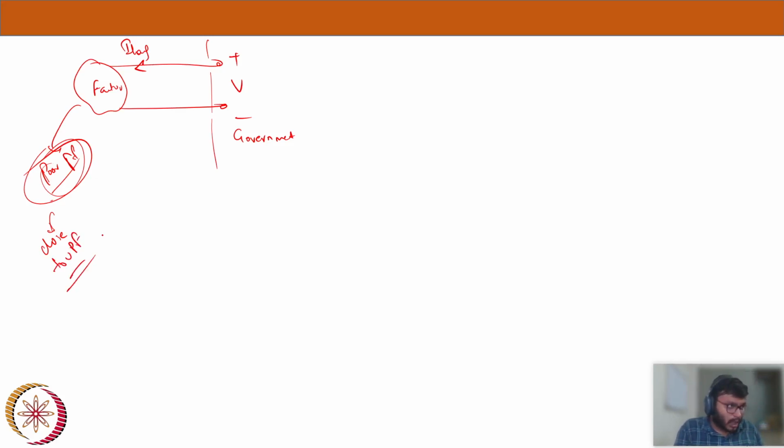Okay, so what will we do? This is the actual motor before. Now it is drawing some lagging power factor. In this condition, let's say this is my voltage bus and it is drawing some I lag. So this particular current I'm showing, this is a lagging power factor, a very poor power factor. Now what will we do? Then we will connect some capacitor at the supply terminals and draw some leading current, because let's forget about the synchronous motor.